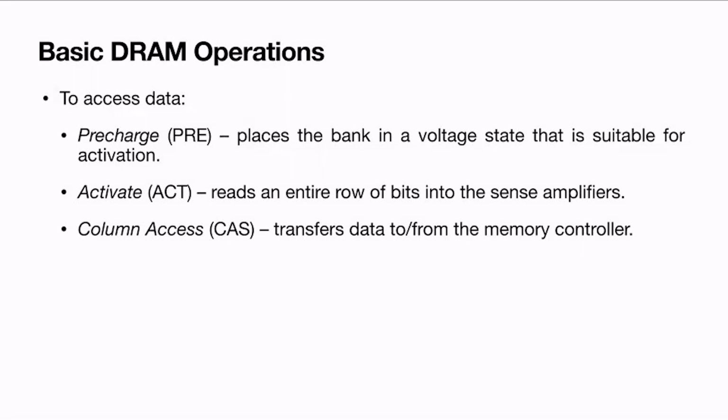And another thing is, as I mentioned previously, DRAM is a dynamic random access memory. The data stored in the DRAM cell is in terms of the charge in the capacitor, and the capacitor gradually loses its charge over a period of time. So unless you refresh it, the data is not going to be maintained. For example, initially you wanted to store logic 1 and you charge the capacitor accordingly.